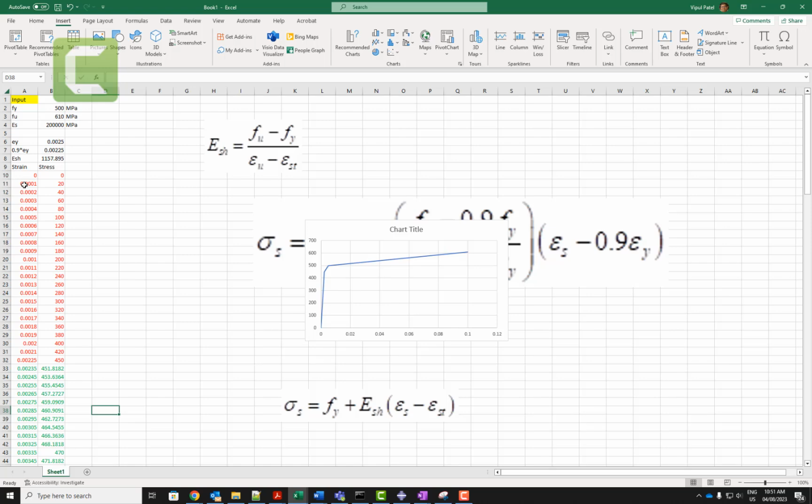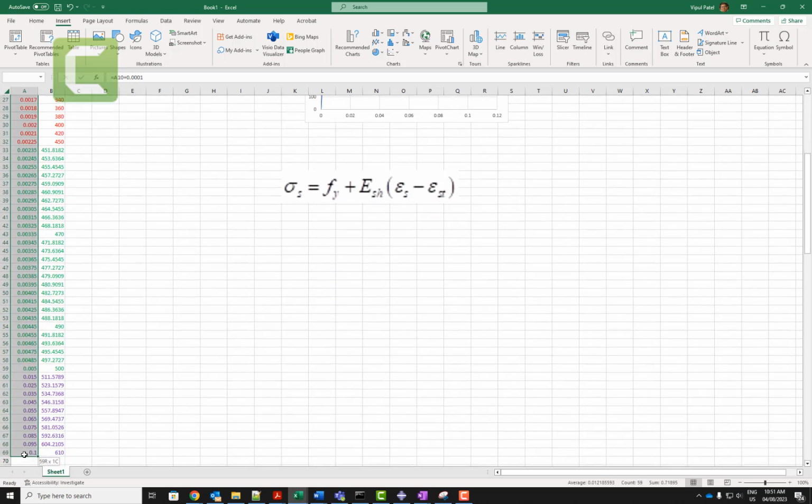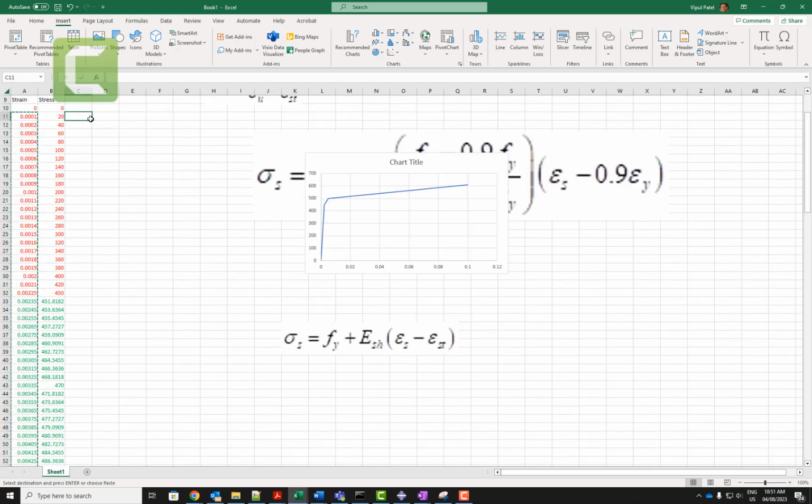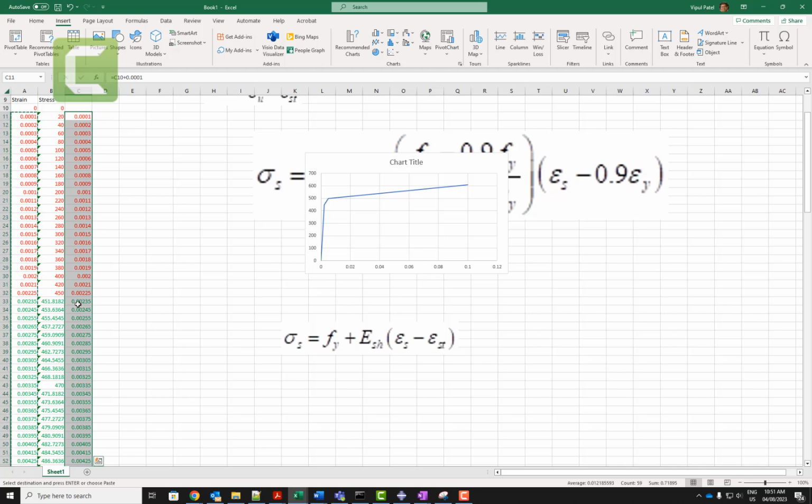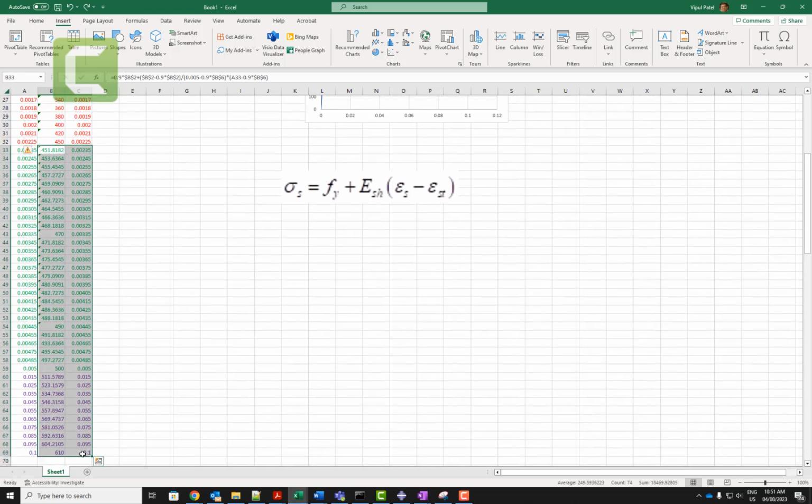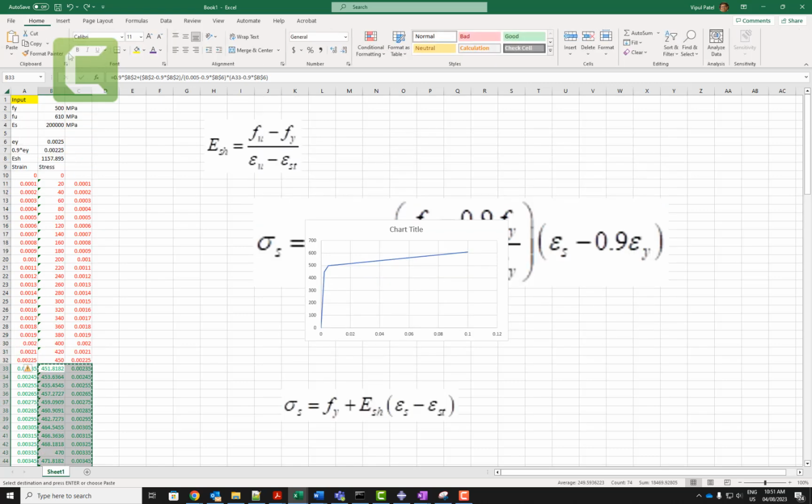So if you want to put it in Abaqus, you can put it in Abaqus with Control V. Probably you want to put it from the plastic one, so you may put plastic strain 0 here. Probably when I do it, I would put it in just copy format. Probably you need to change it into the true stress strain curves. There is a procedure to calculate the true stress strain curve. Please check it. So this one copy, and let's put it in that format, and we put 0 here,